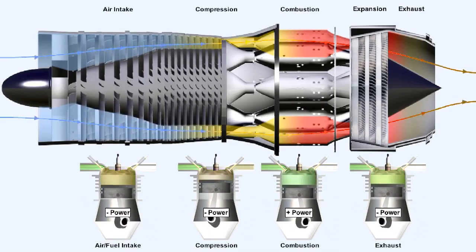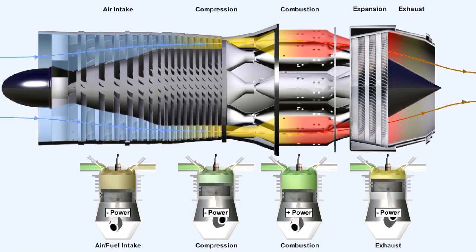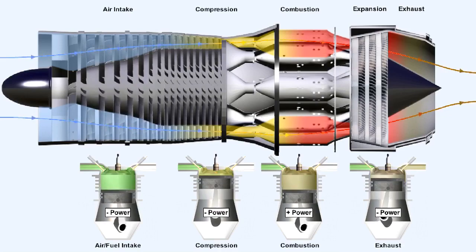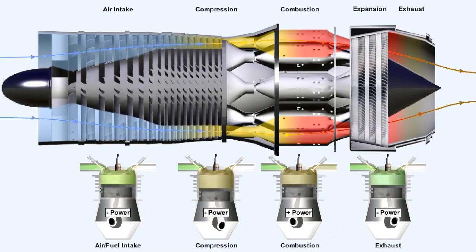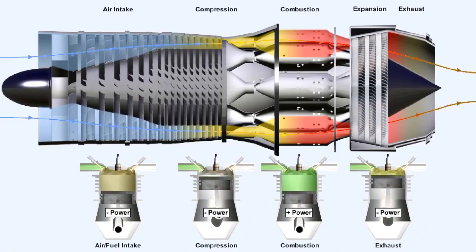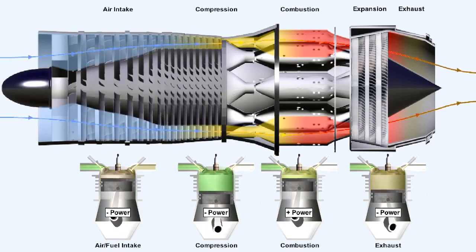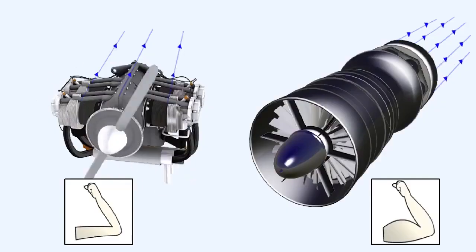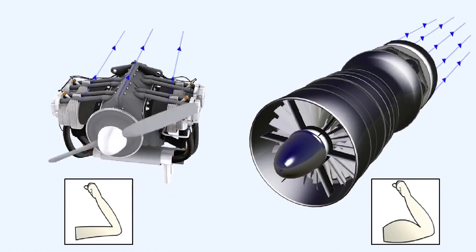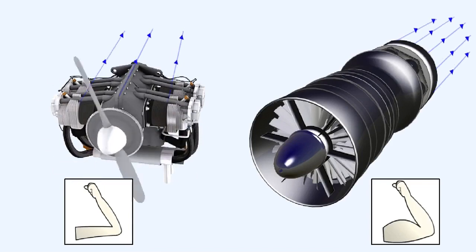In the piston engine, only one of the strokes is utilized in producing power. The other three are effectively absorbing power, while in the gas turbine engine, the 3 idle strokes have been eliminated, thus allowing more time for the burning of fuel. This is just one of the reasons why the gas turbine engine has a greater power-weight ratio than the piston engine.